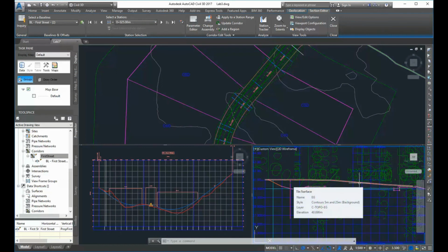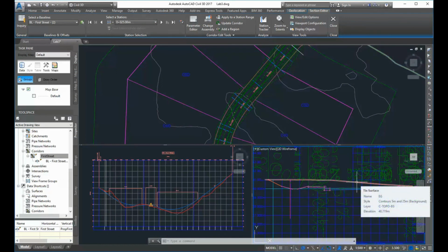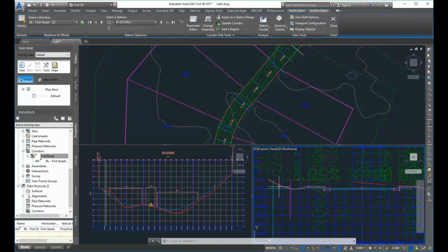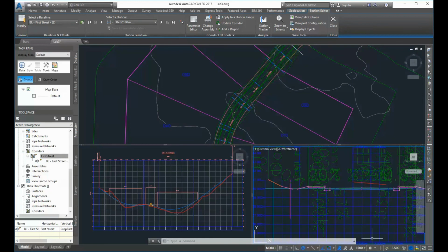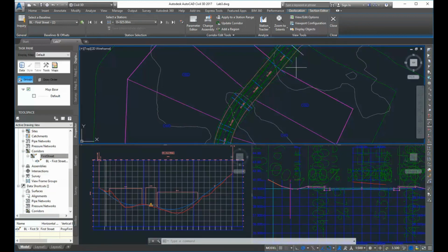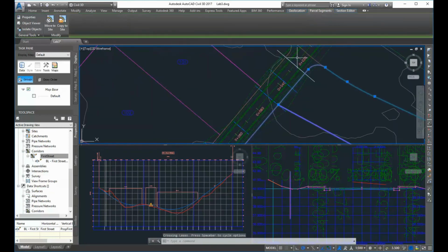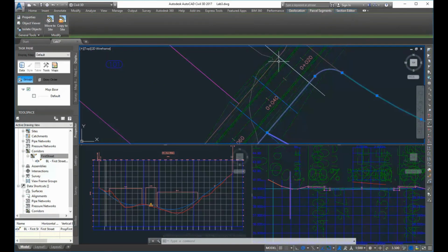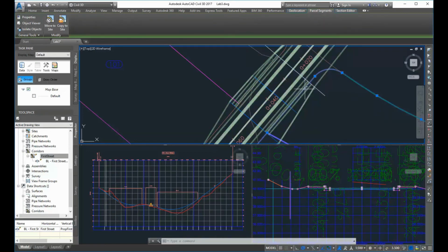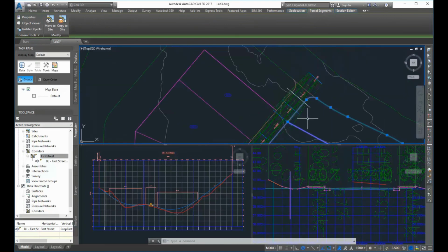We're not going to get too into the transportation or the hydrology or hydraulics of that, but we'll just go ahead with it that anytime it's in a cut section, it's going to put a ditch over there. So, which starts to explain what some of these other lines are that we see. That when we're out here, that it has some ditch sections in there. You can see this is the ditch on both sides, because in both cases it's in cut.